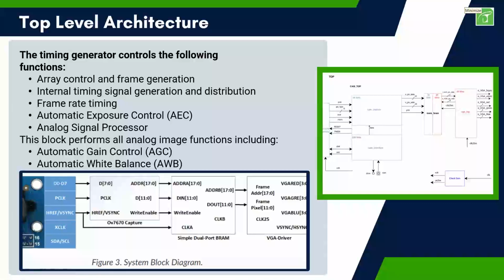On the analog part, like I said, you are using the optical sensing material, which is sensing the light and generating a digital signal based on this. Automatic gain control and automatic white balance are the two factors which are computed by the analog part of this.